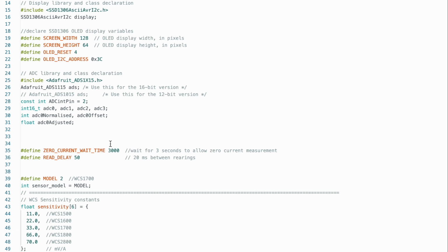And I've got a wait timer that I use. At the moment it's set for 3 seconds, so when the device starts up it waits 3 seconds, especially with this application, things like the speed controllers have a lot of capacitors in there. So I really just want to let those charge, everything settle, measure the quiescent, and then I can use that for the calculations later.